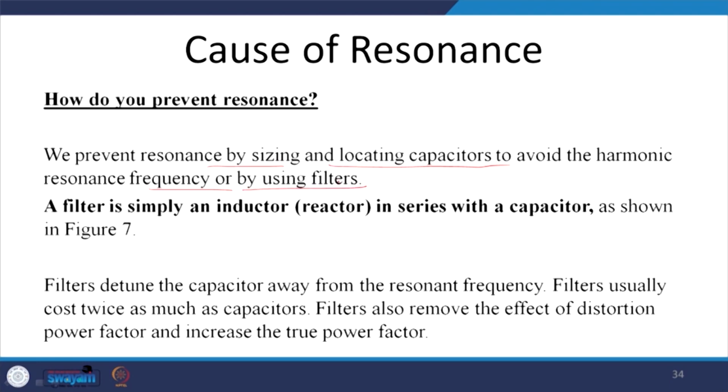filter, and we can use the passive filter and we can use the active filter. In your subsequent classes we shall discuss both the filters, passive as well as the shunt active power filter, and also this static capacitor bank is generally replaced by the STATCOM, and it eliminates this kind of resonance.